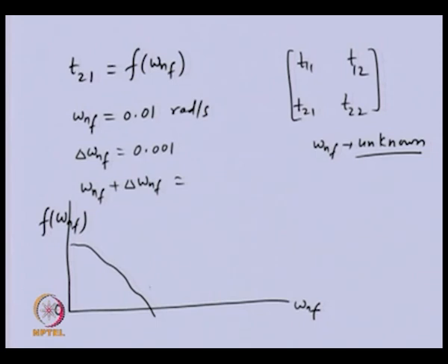So that means this is one of the roots of the frequency equation, and depending upon the degree of freedom it may intersect at different places. So in general, if we have n degrees of freedom, we expect n such intersections to get the n natural frequencies of the system.